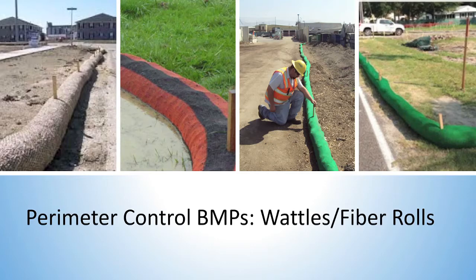All right, other than silt fence, let's look at wattles, fiber rolls. They can be made of natural materials such as straw or recycled materials. They can be artificial pieces of different types of discarded plastic, and we'll get into the compost in a bit. Most of these don't require you to install them in any kind of a trench, although in listening to John McLaughlin talk about all the different ways he's learned over the years to do it, there may be advantages to digging a small trench.